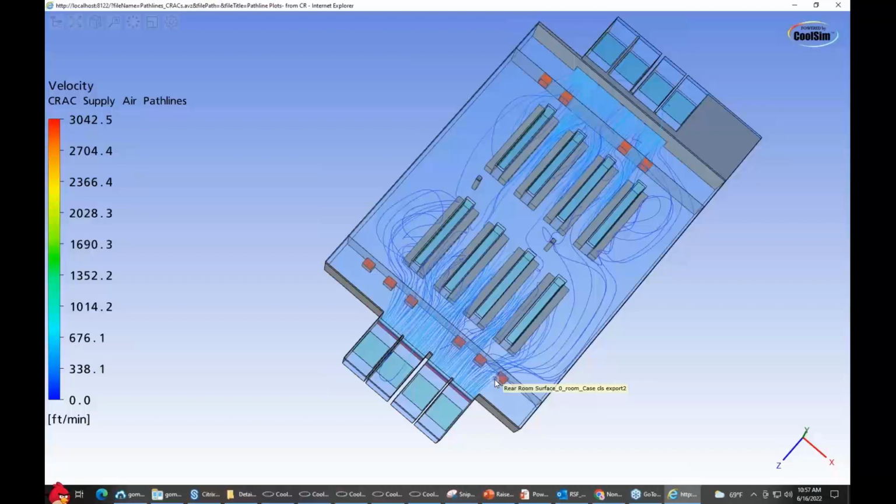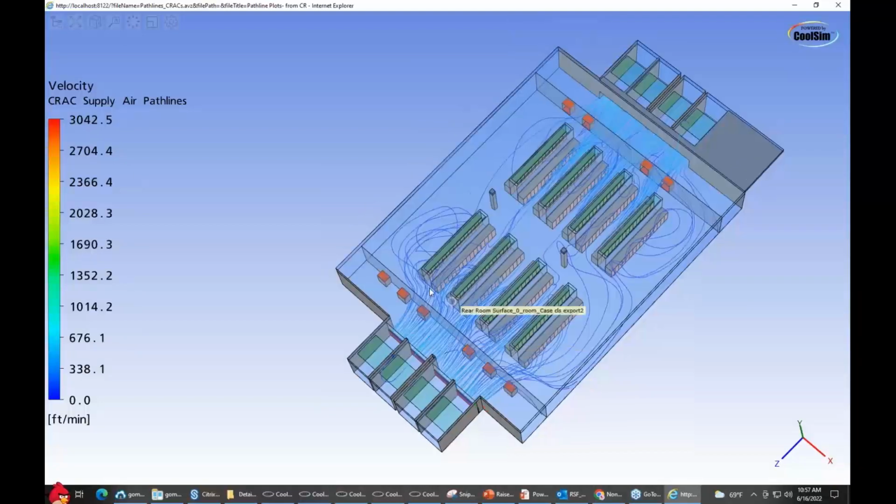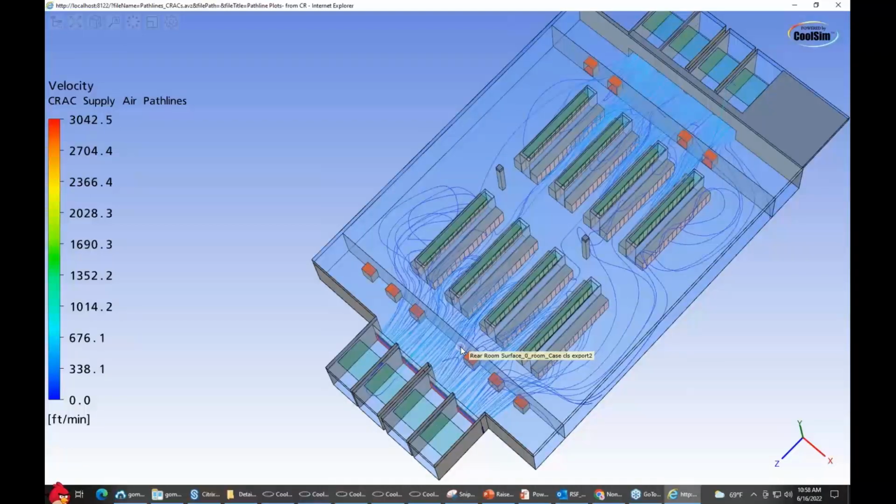In the non-raised floor, you cannot. And what you're at risk of is leakage. As these start to leak, you lose control and the quantity of your cool air, and there's not much you can do about it. So the risk operationally for non-raised floor data centers is that whoever does the installation of the servers and the racks doesn't manage the leakage correctly.